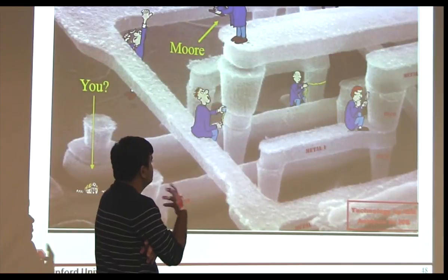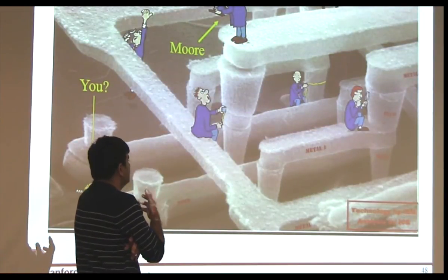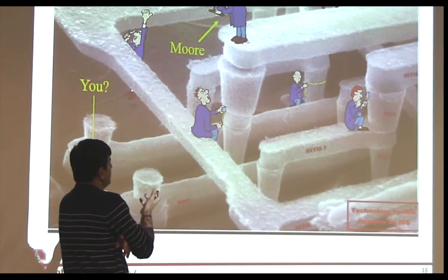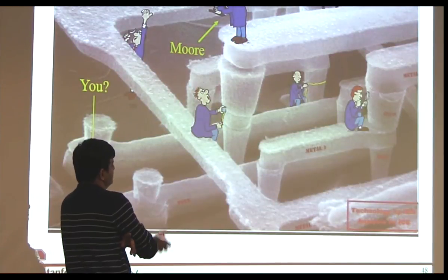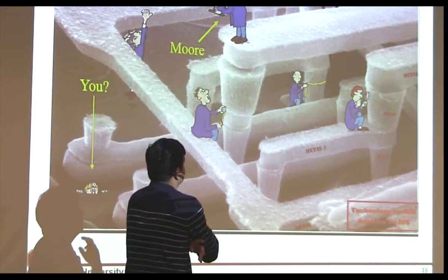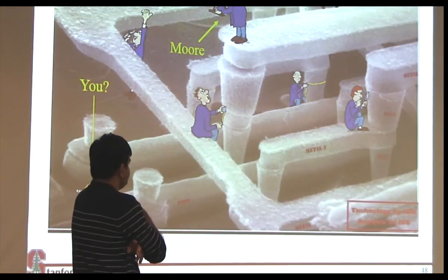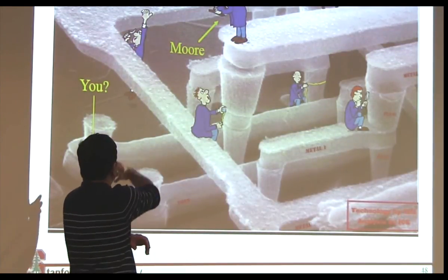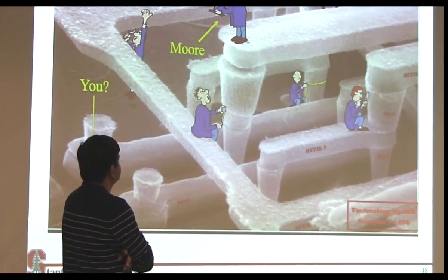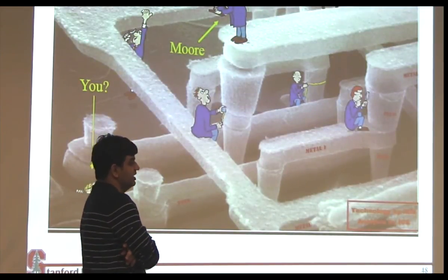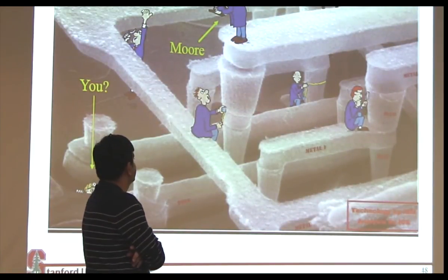So, more important as compared to the transistor delay, what has become more important is the delay coming from your interconnects. So even though you might have a transistor below which is scaling, all the action might be killed by what's happening at the interconnect level.